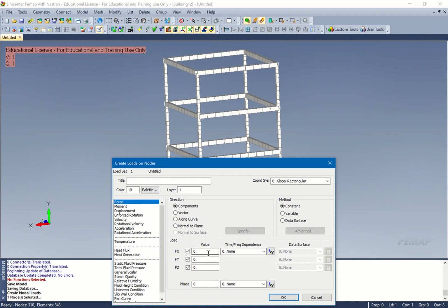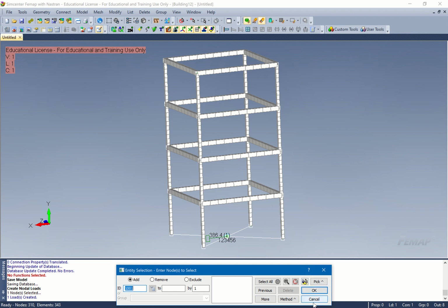First of all, let's do acceleration. So we have acceleration, and the value in the x direction is 386.4. And the time is going to be equal to table D1. Cool, and say okay. That makes sense? Let's put the other two in also. They have to be separate because they all have different functions. If they had the same exact profile, we could make them one file, but they're all different profiles.